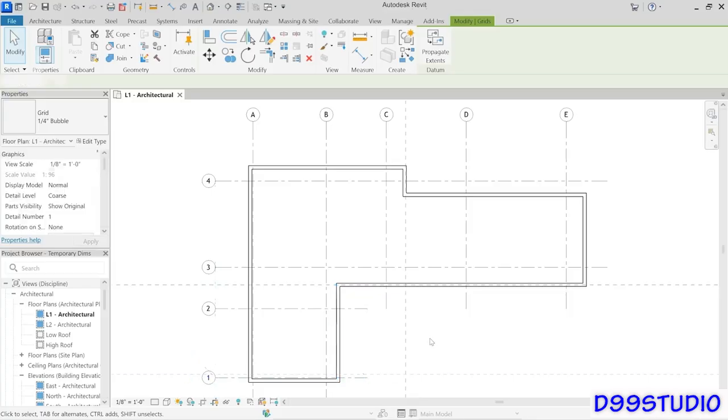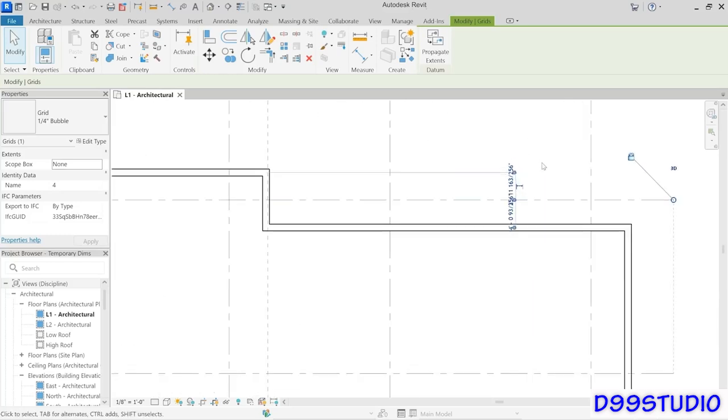Okay, so those are the first two. Let me repeat with this one right here. And you can see it's quite a jumbled mess here. Now, you might be tempted to zoom in, but notice that when you zoom in, the dimensions don't really change, right? The size of everything is still the same. So that can be a little bit frustrating. So you really want to rely on that box that I was indicating to you. And in this case, I want the upper box. And that's how I can ensure that I'm selecting the correct one, 0 space 10 or 10 inches, 250 if you're working in metric.